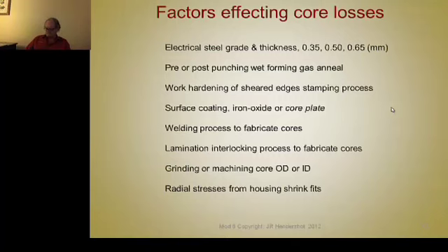The only place you might get a protrusion is where you start the weld. You might get a little tit there where you start the weld or end the weld. So the weld should never be started or ended on the core itself. It should be started or ended on a copper piece right next to the core. So you make the arc on the copper and then feed the torch, the laser or the TIG torch, across at a uniform rate across the stack of lams, and let the arc be broken on a piece of copper at the other end of the core. Then you don't get any buildup at all, and you keep the welds as small as possible.